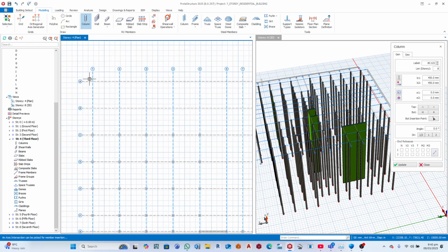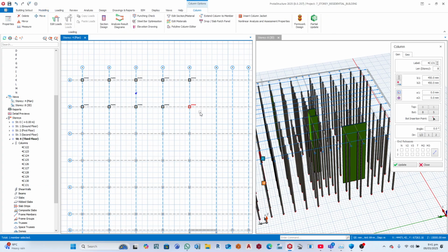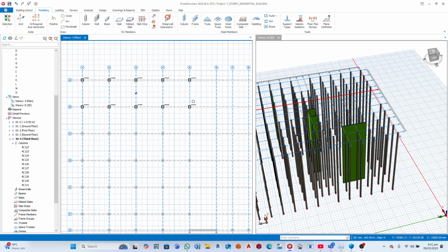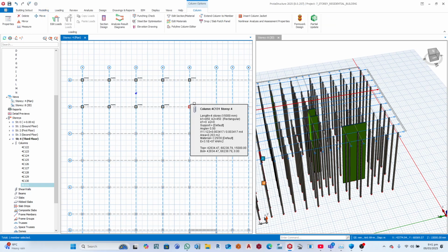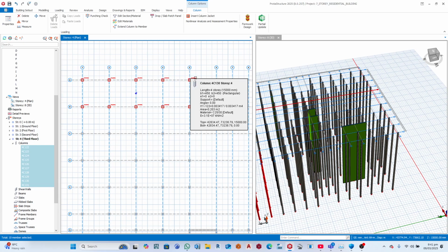So I'll do the same kind of placement I was using, which is highlight, and just highlight around this area. Then it will place the columns on its own. Okay. So when I highlight them, you are seeing what's happening. When I highlight them, then I right click. The same thing I was doing. Right click.